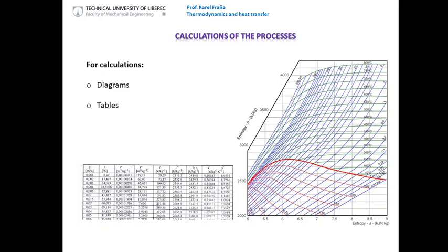And please look now carefully at these diagrams. These other red lines, which are going down, are associated with numbers, for instance 0.95, 0.90, 0.85, 0.80, and so on. This is nothing else than x, the so-called quality of the vapor.